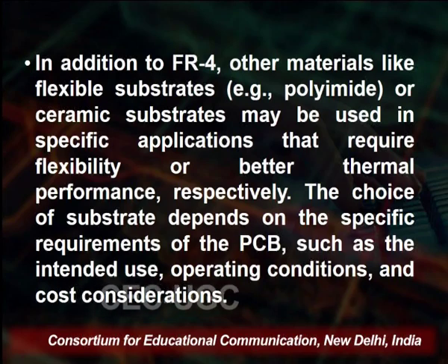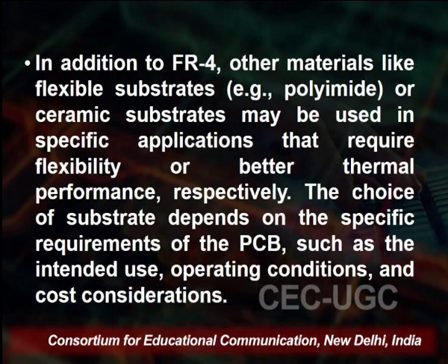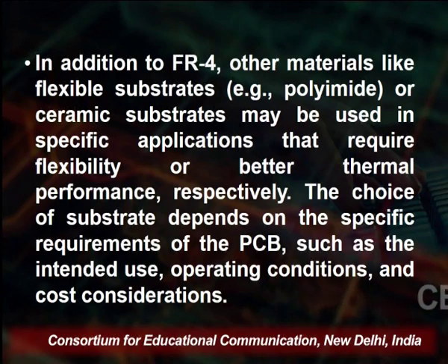So we design the circuitry in such a manner that the function of the circuitry will be continuous and must give the proper result. Besides FR4, other materials like flexible substrates such as polyimide, or ceramic substrates, may be used in specific applications as required for flexibility or better thermal performance respectively. The choice of substrate depends upon the specific requirements of the PCB, such as the intended operating conditions as well as the cost.